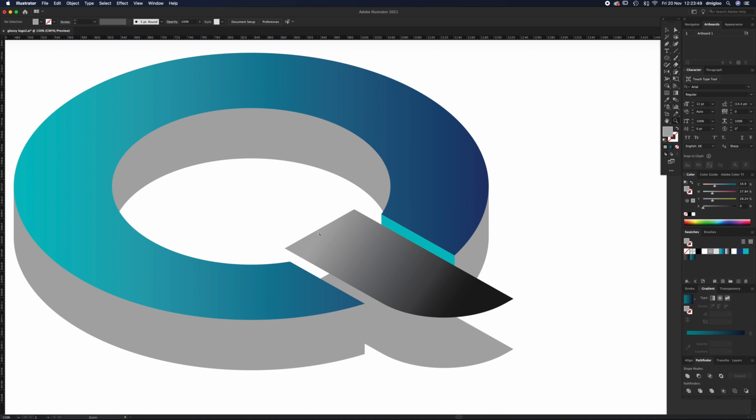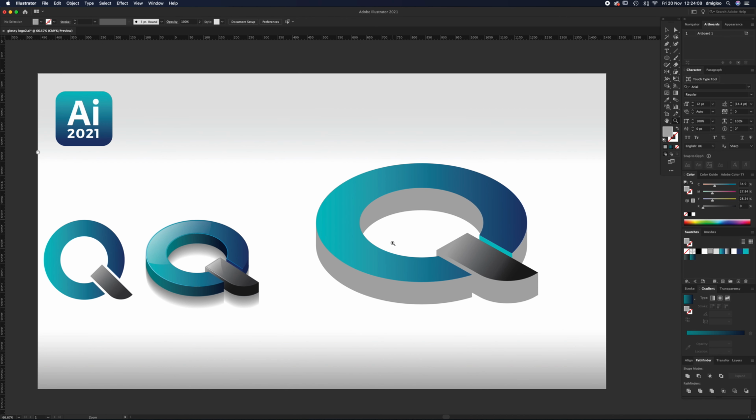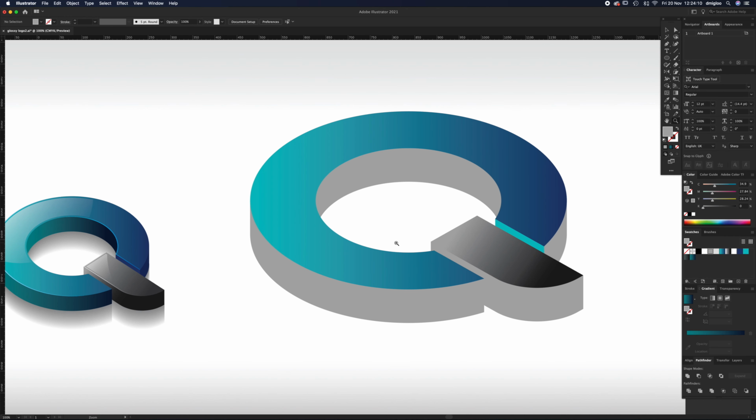And there we go. So now we've got this one to do. Select this object with A, click this one, drag it to that point, and press P, and we're going to add in. So when you go over this line, you'll see the plus appear, direct select, and drag it to that point there. So now we've got our 3D object underway.